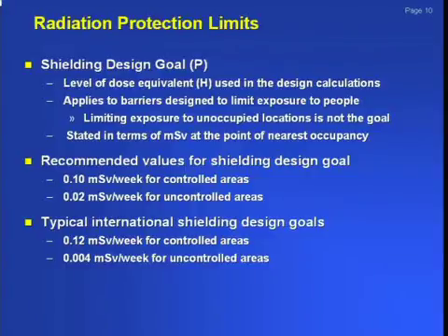And sometimes you have to really reiterate that: you're doing a shielding design to occupied space. If you have an air conditioning shaft or an elevator shaft, you really don't need to worry about the shielding in that shaft, only if you're going to have people in there. And so you can have sometimes strange situations come up. And again, look at where your closest occupied area is.